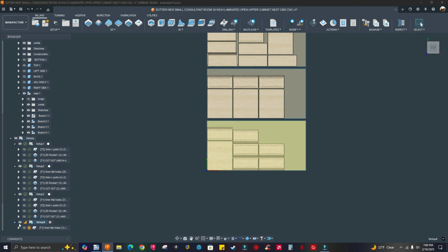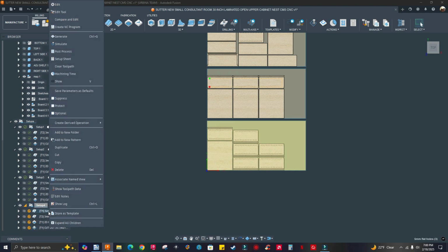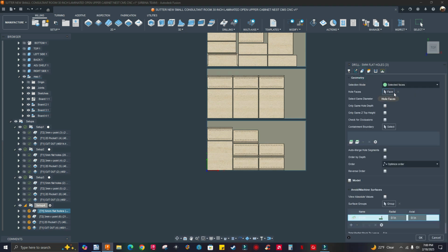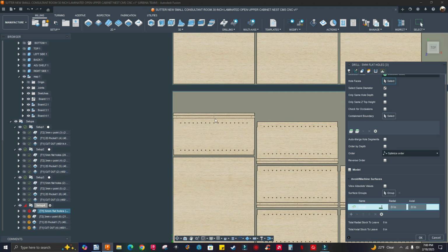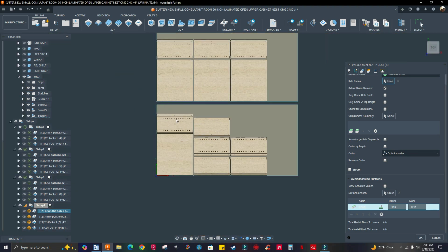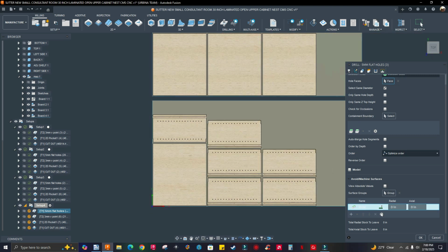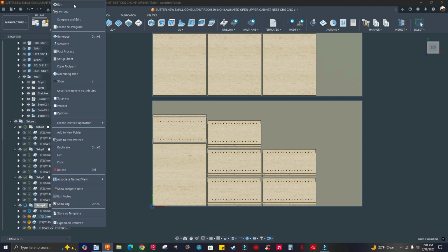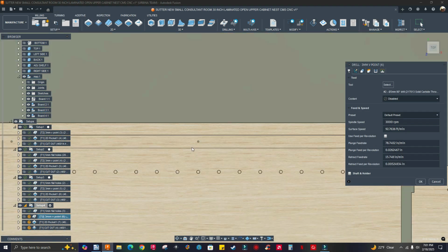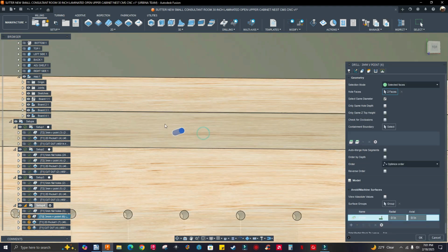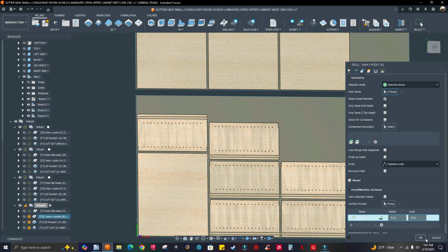Click on this arrow, okay, right click on the first one, edit, go to geometry, right next to face, click on this X to clear that out, zoom in, select this face, zoom out, just to make sure everything else is selected. That's 5 millimeters. Click OK. Next one, right click, edit, zoom in, gonna select this face. Well, it's hard to select it, so I'm gonna rotate a bit, select the face, zoom out, click OK.